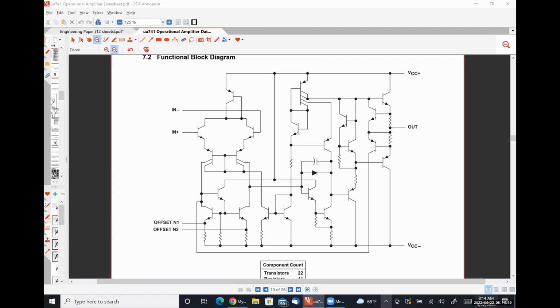So that's where op-amp rule number 1 comes in. For a lot of op-amps, they might be based on a MOSFET or metal oxide semiconductor field effect transistor topology. The input resistance of a MOSFET-based op-amp is typically on the order of tera ohms. So the currents in those types of devices are even smaller.